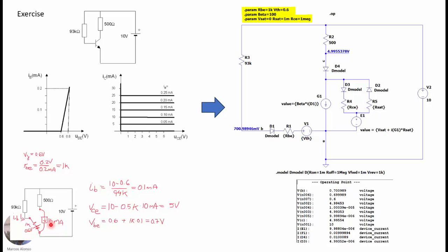In this case we don't have resistance in parallel with the current source, and we do all the analysis and so on. So in this case, we can use our BJT model to do the simulation and verify that everything is correct, and we will obtain the same values for the collector voltage, for the base to emitter voltage, for the current through the base, and so on, exactly as we have done in our analysis considering the piecewise model.